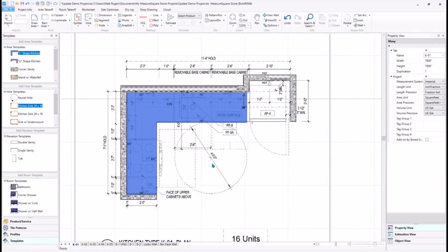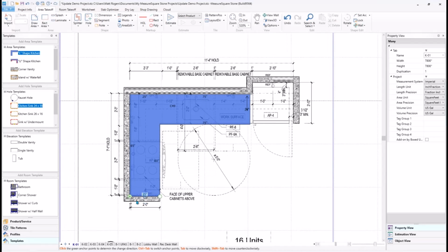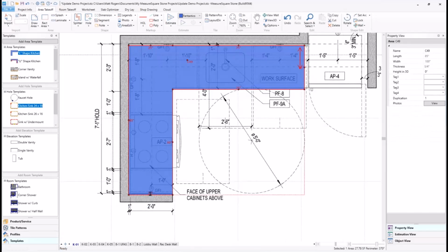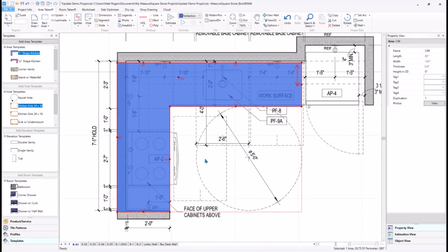And one other thing you might notice, when I'm making these changes, you can actually see there are these two circles, one with a little colored green dot in here. This is actually my anchor point. So if I wanted to select this edge and maybe change the dimension from this edge, again, if I make this 30 inches instead, it's going to actually push this out from the right to the left side now, instead of the previous dimension before. So we have a lot of control now in which way all these edges pull or push in relation to the other edges here as well.